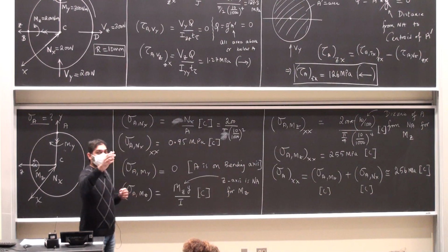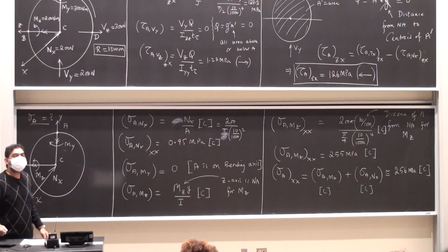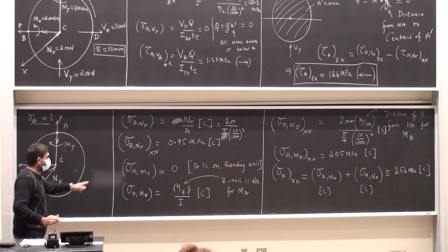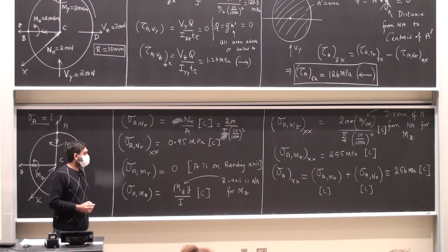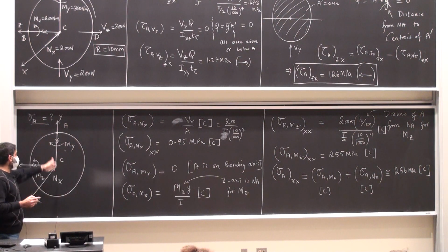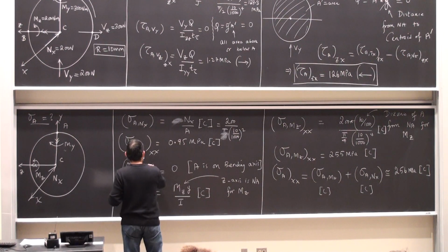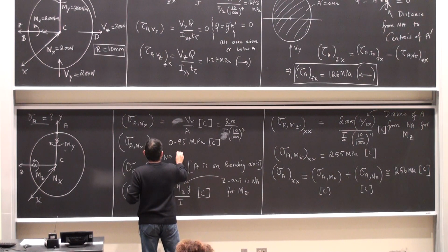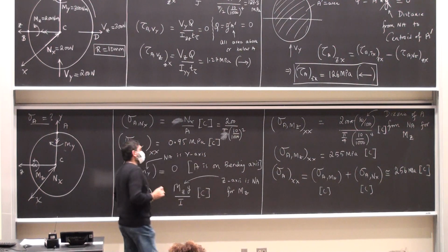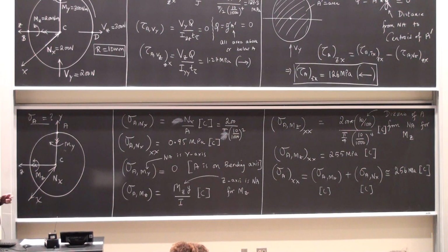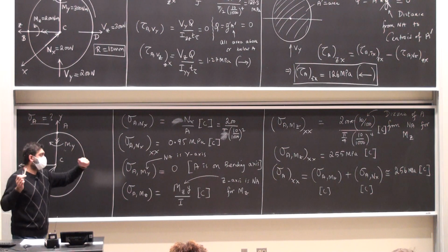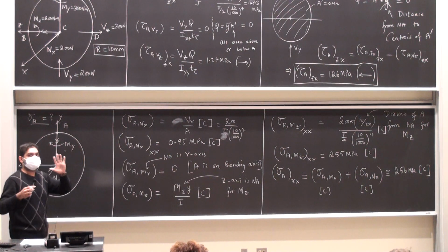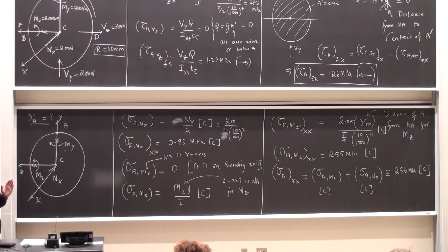Okay. Yes. For the bending stress of A with respect to My, is the neutral axis still the z-axis? No, for My, the neutral axis is the y-axis. If you want me to write it out, so. The way to remember this, and I think we've discussed this before: if you're looking at shear forces, the neutral axis is an axis perpendicular to the shear force and on the plane of the cross section. If you're looking at bending stresses, the neutral axis is the same as the bending axis. Okay, in this case either the z or the y-axis, depending on which bending stress you're looking at.